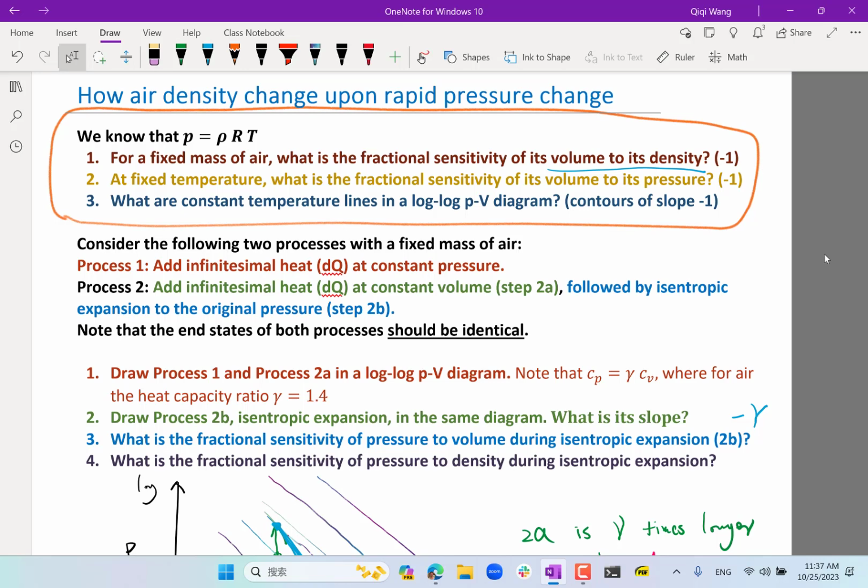But the time it takes for air to flow from, let's say, the upstream of the airplane to a low pressure region above the wing and then to behind the trailing edge, the time it takes for air to go through that path is actually very fast, a small fraction of a second. And there is absolutely no time during that time for conductivity to either add or subtract any noticeable amount of heat to that air.